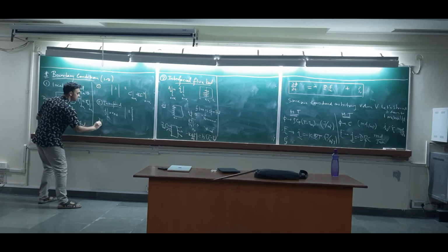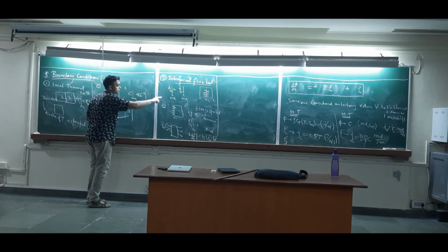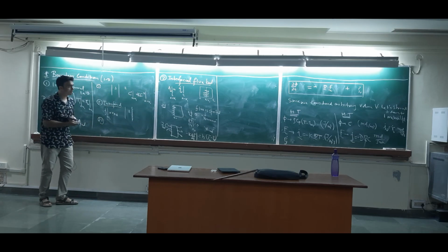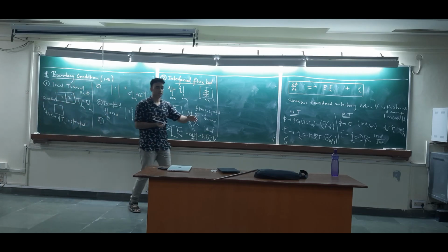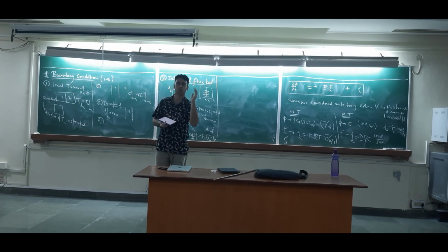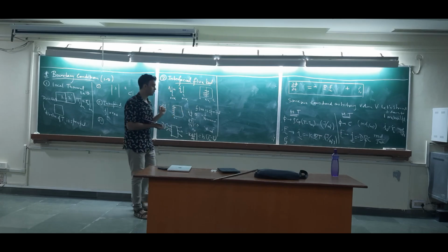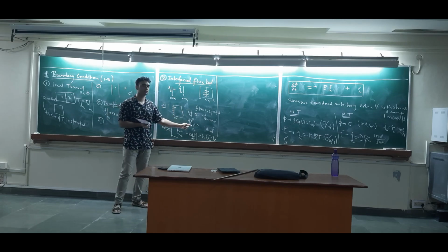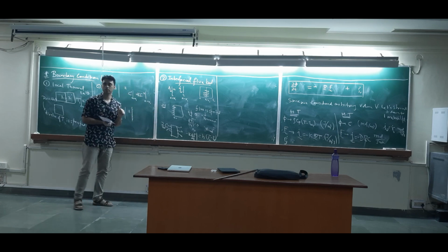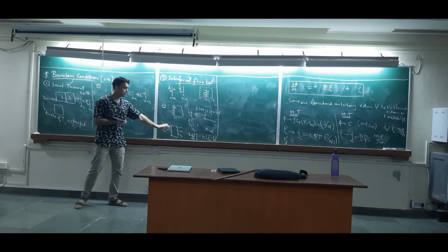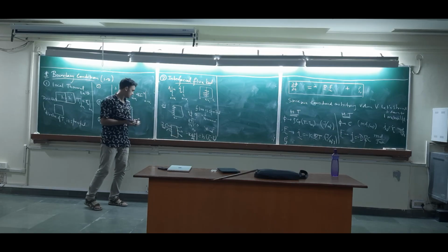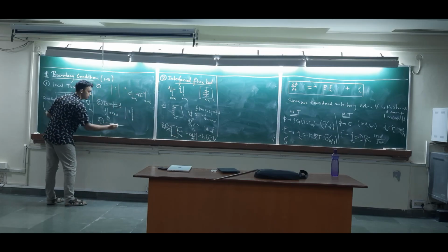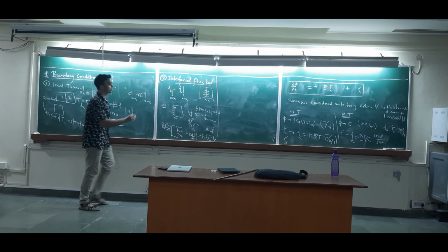Since I made two types of these interfacial boundary conditions, I could again make a Neumann type boundary condition, meaning this is my liquid film, one side is solid. Diffusion in solids is very, very low, so it's almost an inert surface. So similarly, you will have dou C by dou X equal to 0. So you could have a Neumann variant of that, or you could have this variant. So 2.1 is fine, I'm not going to write it. 2.2, let me write.